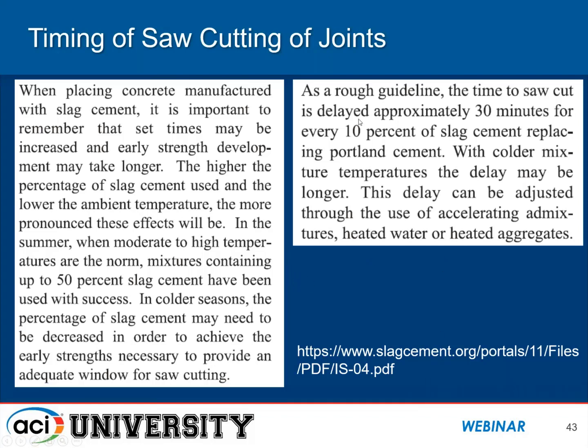As a rough guide, the time to saw cut is delayed about 30 minutes for every 10% slag replacement in the mixture. And that may be made worse by lower temperatures. Again, there's more information on the website about this.